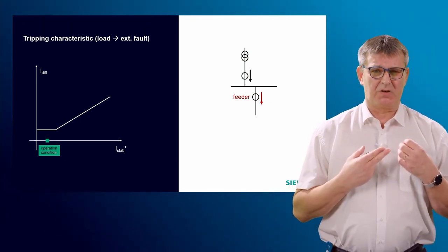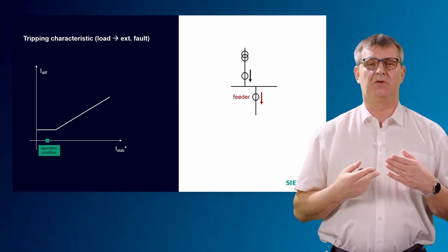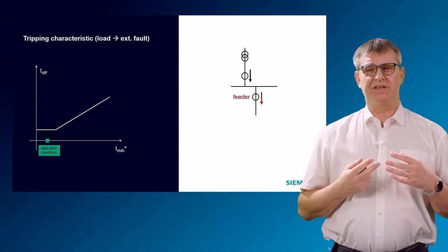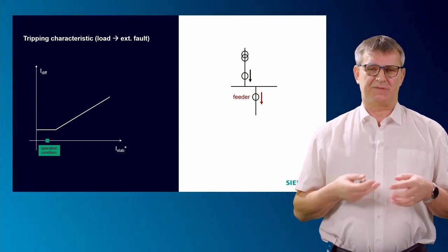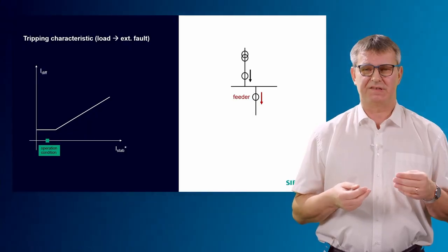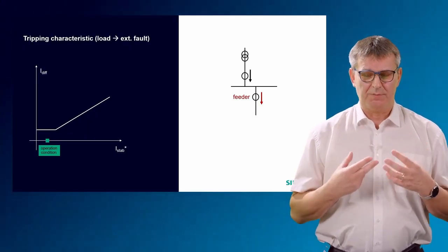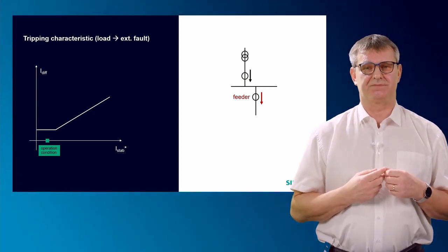And it's very important to understand, we will see more examples with only two feeders, that two feeders is every time the worst case scenario, especially if we come to CT saturation. So an example with only two feeders is the worst case example, and all others with 3, 4, 5 feeders are not as important and not as difficult as an example with two feeders.